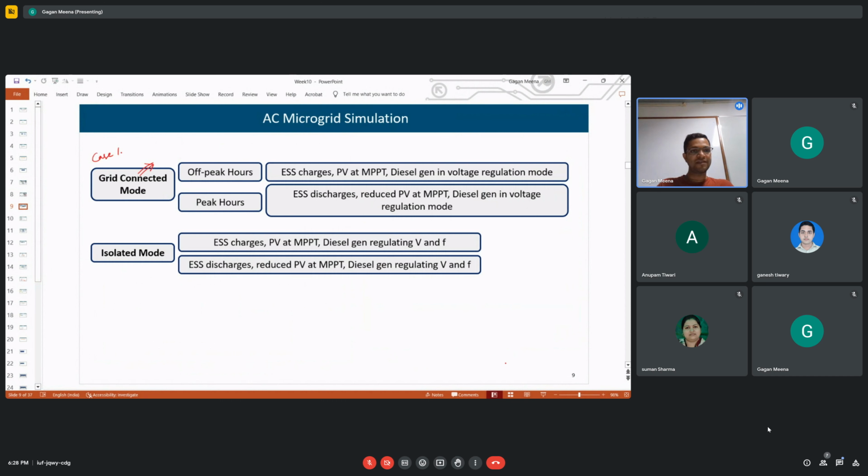And all the fast acting devices are considered for Q along with slow devices. So out of the available devices for voltage regulation, some are very fast. They can operate within milliseconds and some may not be able to do that. Let's say OLTC. OLTC is a mechanical device. So there are taps on the transformer, online tap changing transformers. The taps are mechanical. Mechanical systems are always slow as compared to the other converters.